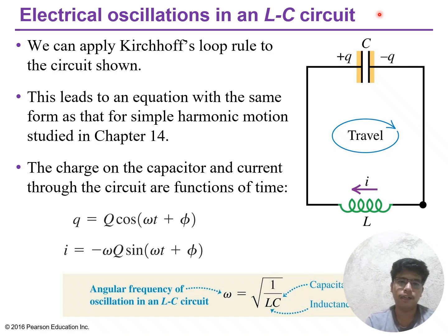So angular frequency omega equals 1 over the square root of LC. Its oscillation speed depends only on L, the inductance in henries, and C, the capacitance in farads. As you can see here, the current travels clockwise, and then counterclockwise, creating an AC oscillation. No resistor means energy is conserved forever, ideally a pure electrical pendulum.